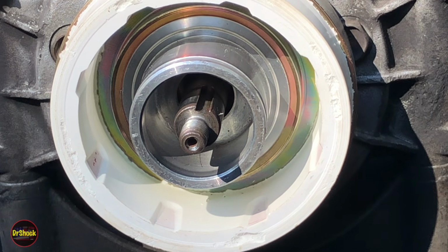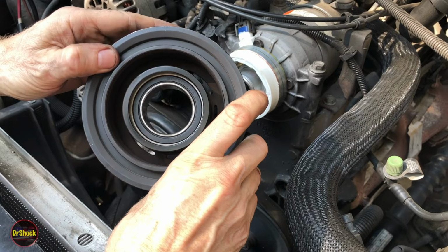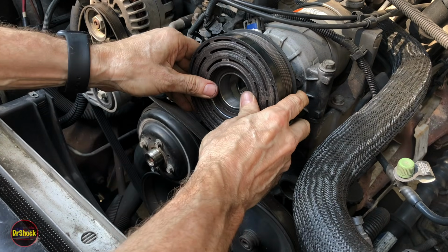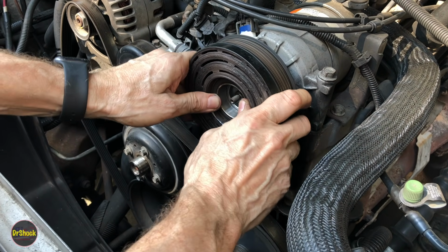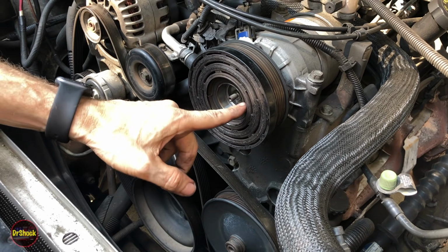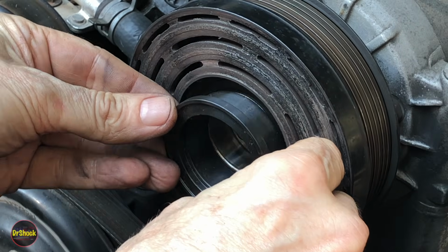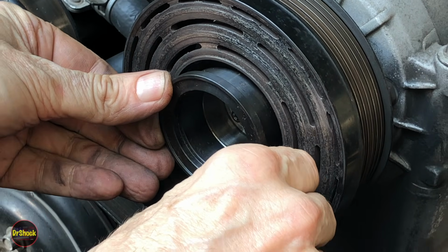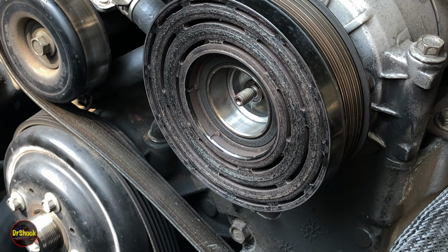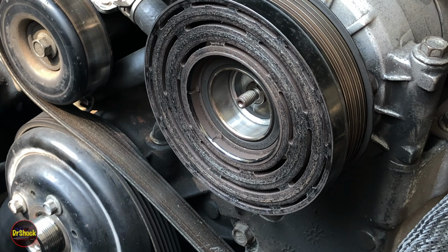All right, so now we're going to position our pulley. So let me go get the pulley and we'll put that back on. All right, we did the same cleaning out of the bearing surface. A little bit of 3-in-1 oil. Now on this guy, you want to be sure that you're hitting the inside race and driving that on. So there's another special adapter that goes like this to get that started. So we'll start it with the dead blow hammer, and then we'll put it the rest of the way with the brass hammer.